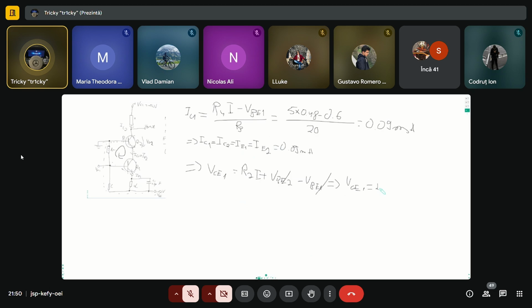So 20 times 0.48 is equal to 9.6. 9.6 volts. Okay. Oh yeah, and since this is bigger than VBE, it's forward active region, as he likes to write on the board. Okay, so far.